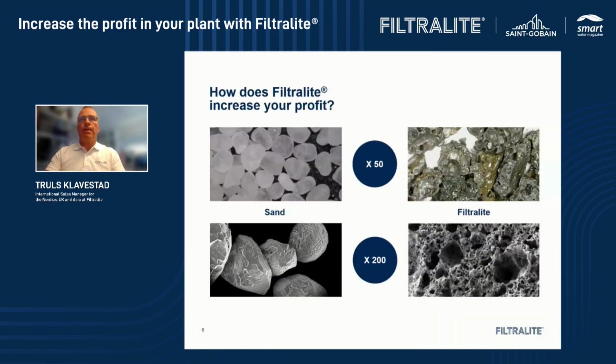So if you make a comparison between sand and Filtralite, the reason to compare with sand is because sand is the most used filter material worldwide. If you look at how sand looks, it looks more like a round particle. And the only way that the turbidity or suspended solids coming into the filter can be caught is between two sand particles.